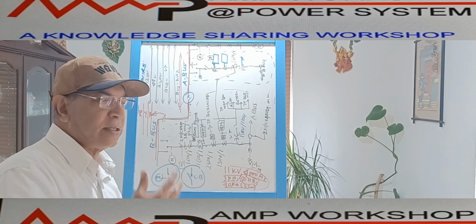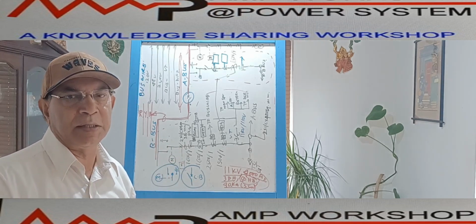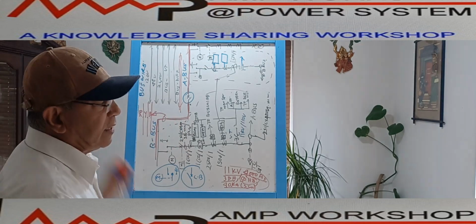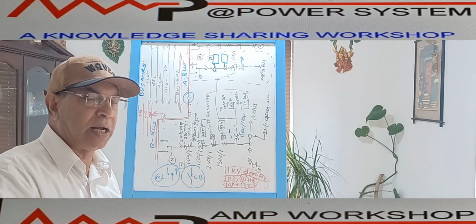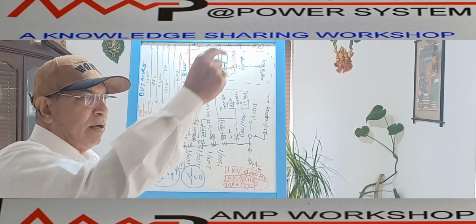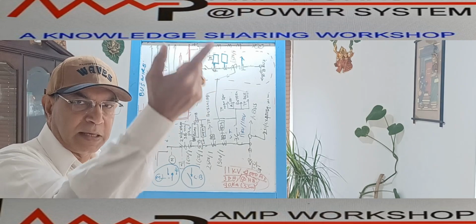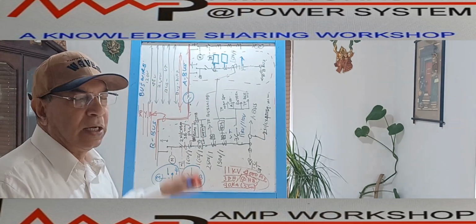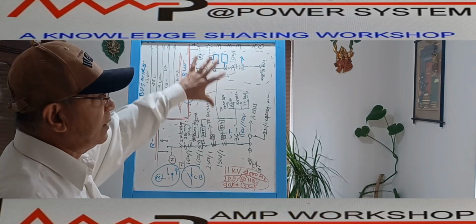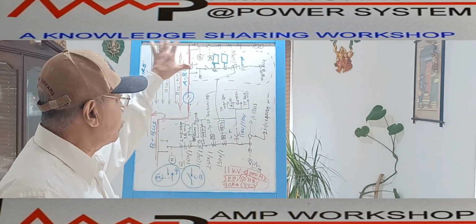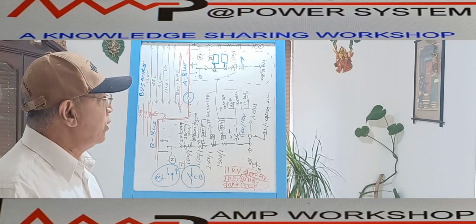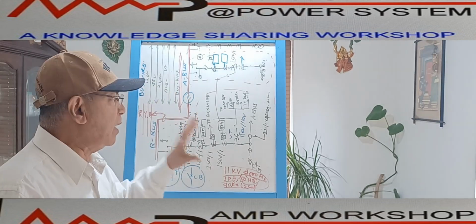So in this case, what is the incoming feeder? Incoming feeders are all the generator feeders, and if this switchgear is hooked up with another switchgear which can supply power to this switchgear, that will also be considered an incoming feeder. That means if there is an overhead line or some other substation bringing power to the switchgear, that feeder will be considered an incoming feeder. So we are considering this an isolated switchgear. That means it is an offshore or some island switchgear where there is no utility power supply, so this switchgear is only supplied by the generators.